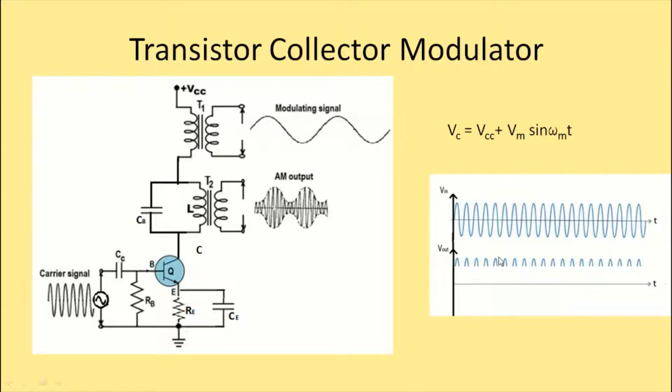So the signal here, you see that it is not continuous. It is there for some time and then not there for some duration. Again, you can see the signal for some time, then again the signal is not seen for some duration of time. So this type of discontinuous signals, you call it as spurts of signal. S-P-U-R-T-S, spurts of signal. And these spurts are seen at the collector end, that is at this point. So this is how the class C amplifier works in brief.